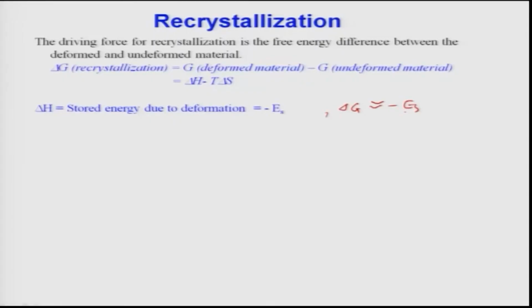Let me also tell you a few important facts about the recrystallization temperature. Obviously, as I told you, the higher the temperature of metal working, the lower the strain energy stored, because recovery will happen subsequently as strain energy will be relieved, and this will lead to a higher recrystallization temperature.